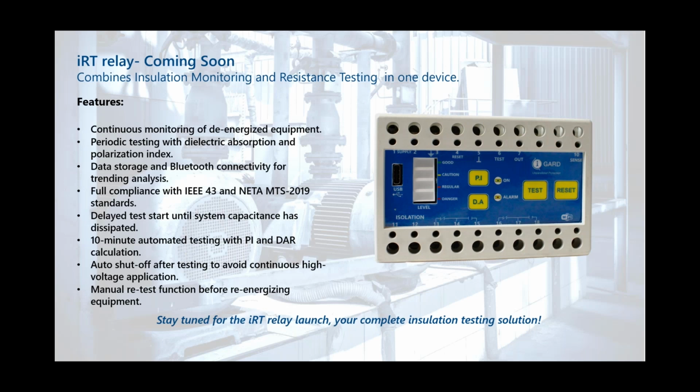So at I-Gard, we are using our IRT relay, which is coming soon, and it combines insulation monitoring and resistance testing in one device. It provides continuous monitoring of de-energized equipment, and periodic testing with the dielectric absorption and polarization index. We have data storage and Bluetooth connectivity for trending analysis, full compliance with IEEE 43 and NETA MTS 2019 standards, as well as delayed test start until system capacitance has dissipated. So you saw on the graph previously, we were waiting for that capacitance to drop off in terms of its current, and a 10-minute automated testing with PI and DAR calculations.